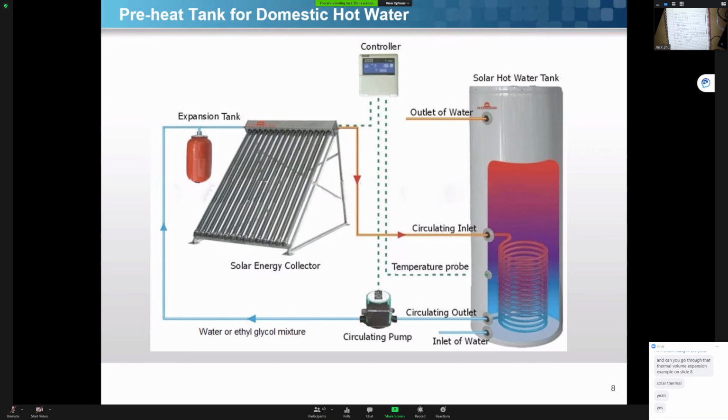I'm not sure if you guys did this in the code section. Even in the code, there is talk about when you have PVC pipe connected together, after a certain length you're going to put an expansion joint in there. So even a solid piece of material will expand when it warms up.